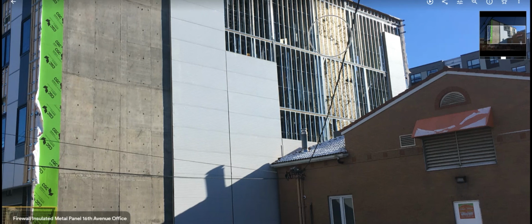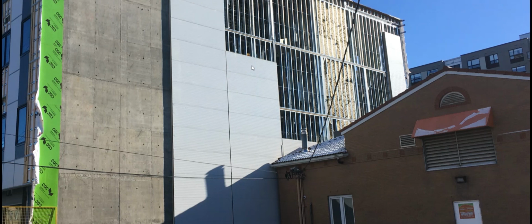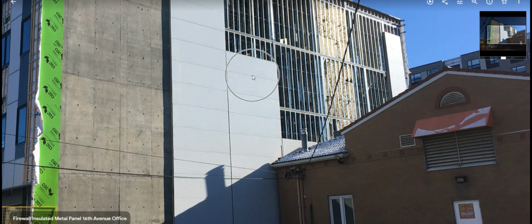And if you insulate in the stud space, you're making that inside face of the insulated metal panel colder. You wouldn't want that, because then you might again get condensation forming. So if you were going to insulate the stud space in front of this insulated metal panel, then you'd probably want to put a vapor barrier on the inside. And then all of a sudden you've tanked your wall, because you have a vapor barrier on the inside, and the metal on here is going to be a vapor barrier as well.